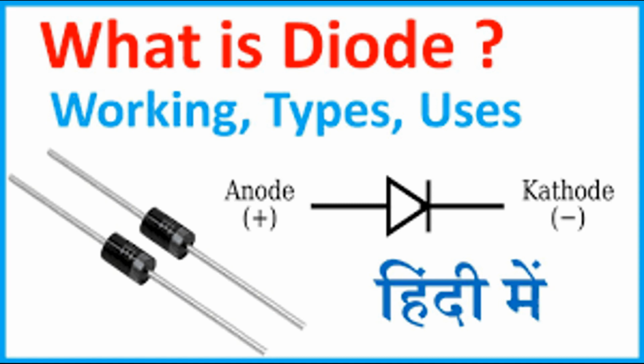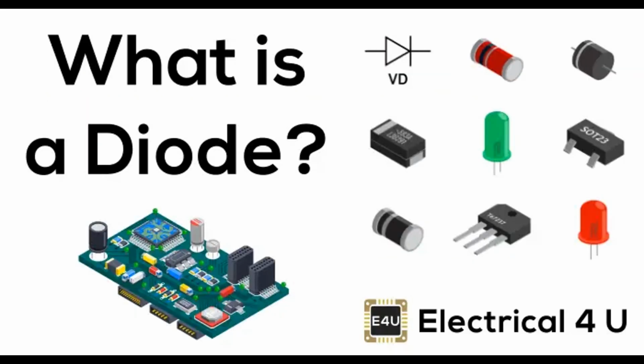Flyback diodes. Freewheeling diodes in circuits with inductive loads such as relays, solenoids, or motors. Flyback diodes, also known as freewheeling diodes, are used to protect against voltage spikes that occur when the inductor's magnetic field collapses. These diodes provide a path for the inductive kickback current to circulate safely, preventing damage to the rest of the circuit.